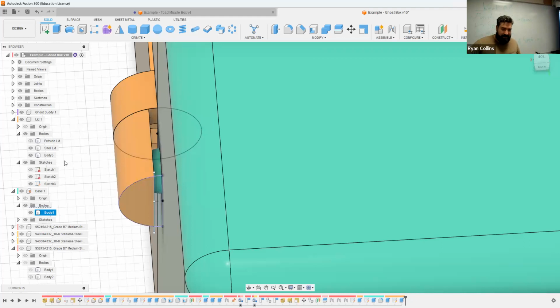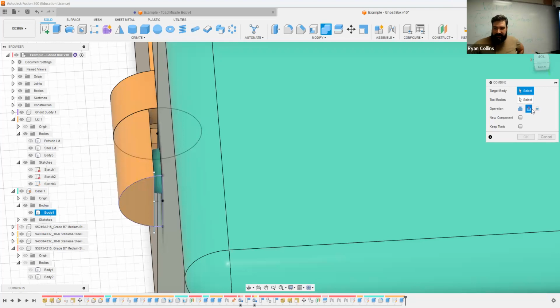So now the last thing I need to do for this is I want to use essentially this bump that is attached to the body. It's all there, all one thing. And I use that to cut a little divot away from my little latch here, a little cover. So with everything active, I use a combine and cut tool.